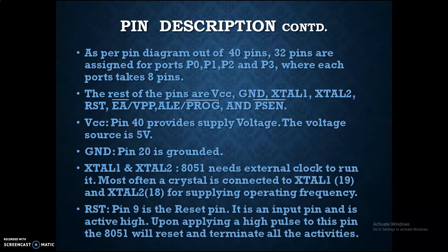Out of these 40 pins, 32 pins are for input output operation. That is P0, P1, P2 and P3. Each port contains 8 pins. The rest of the pins are like VCC, which is connected to plus 5 volts, the activation voltage; ground, which needs to be grounded; XTAL1 and XTAL2, which are pin number 18 and 19, which need to be connected with the crystal oscillator; and the reset circuit.